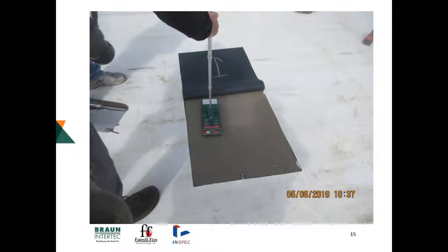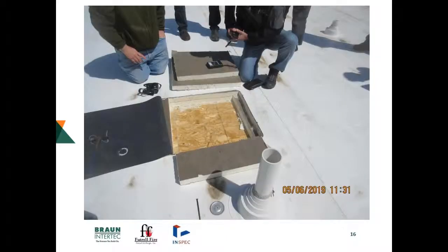Different methods of monitoring for moisture. This was an area where the roof membrane was peeled back. The device on there is a Tramex meter that measures kind of a voltage between two pins to give you a moisture content. And even this was running at a high moisture content, and you don't really see standing water on it. This was directly below it as well, and the roof deck looks fine, but it was at an elevated moisture content of about 20%.